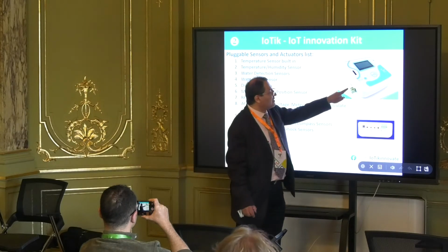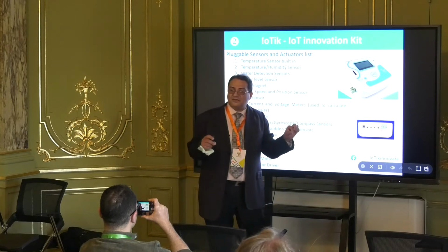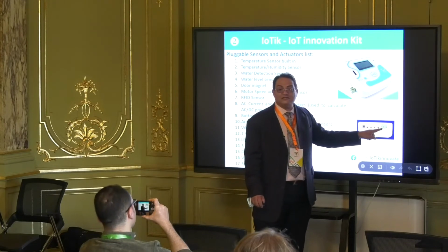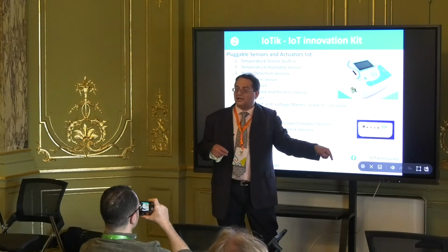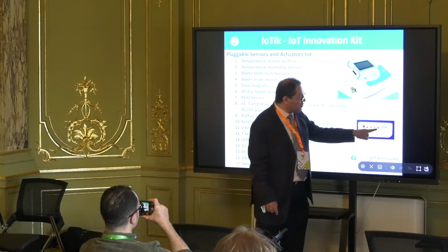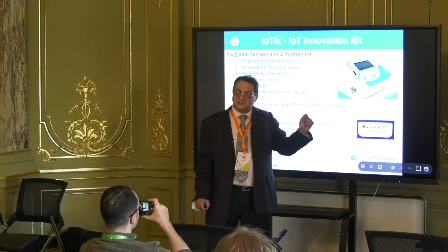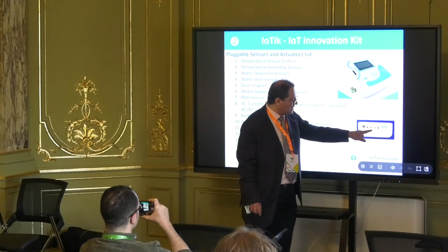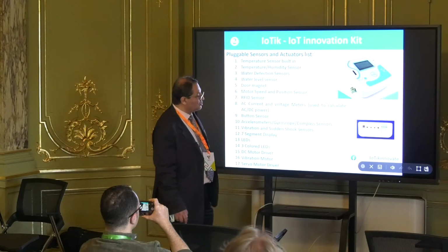It has current sensors, so you can measure the current passing in an electricity wire at your home. It has 2 power relays, so you can control lighting at home or control the lighting in a pool. We will see this in the examples. It has also 4 external connectors for temperature and humidity sensors that come with the IoT device, another plug for the proximity, another plug for IR, and one for the water level as well.